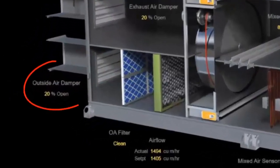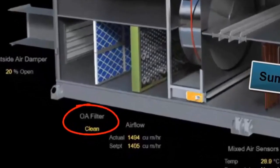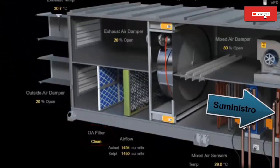1. Damper opening percentage, which controls the entry of outside air. In this case, it is at 20% open. 2. The sensor that measures the pressure drop in the filter is in charge of indicating the state of the filter. To do this, it compares the pressure after the filter with the one it had before. If the drop is high, it means that it is clogged and requires maintenance.